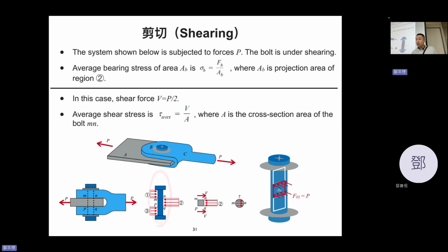Blue bolt, right? And this gray material trying to go to the left, what kind of stuff stops it? So you can imagine that the bearing means stop it. Okay, bearing in Chinese is 承载、负载, it bears this force, it blocks it. So you can imagine that the white shape is going to the right, the gray material going to the left. What kind of stuff stops it? The dark blue bolt, okay.